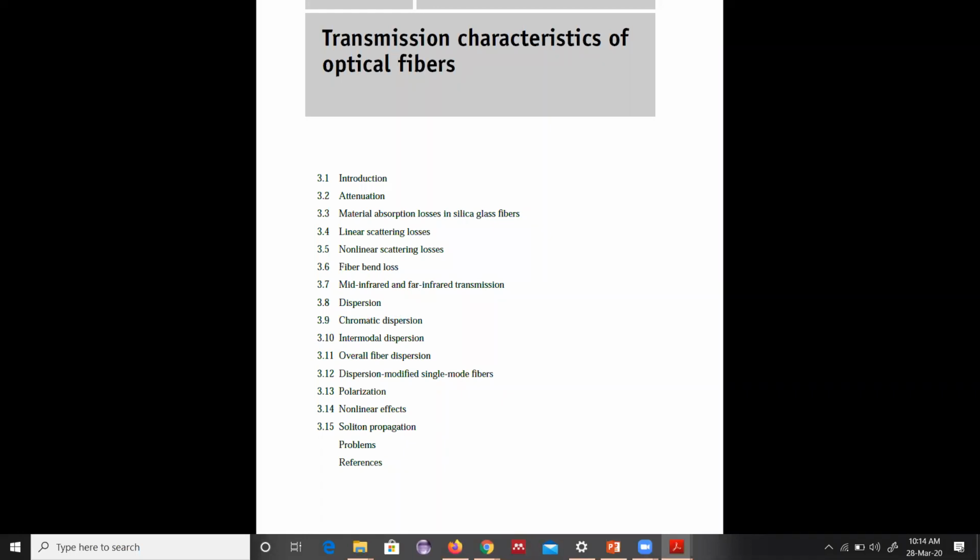As the dispersion increases, the bandwidth that is being offered by the optic fiber cable will reduce. And as the pulse gets broadened, and if you are transmitting multiple pulses, the pulse will get overlapped on the other pulse, that results in intersymbol interference also, which contributes to reduction in the bandwidth.